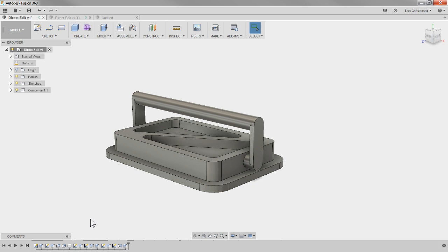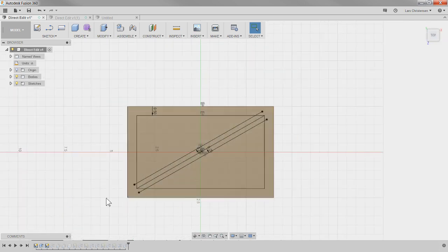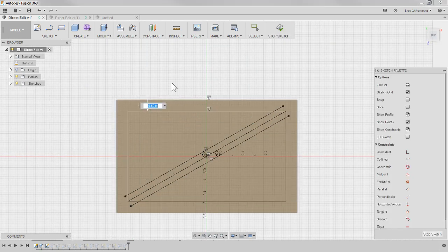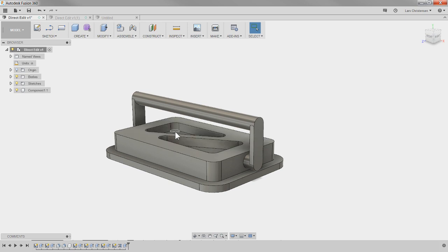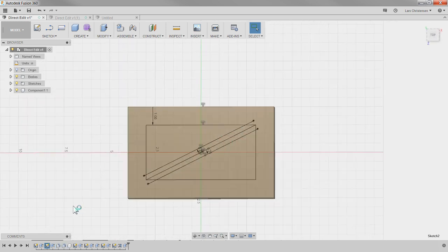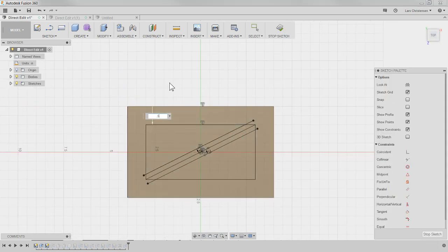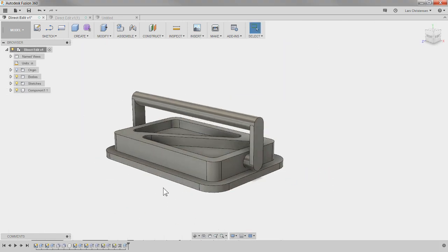So you can go in and change the sketch. If I go into this sketch here, say edit sketch, we could for example change the offset dimension here, make this 1 inch, and now when I get out of it, these 2 pockets got smaller, and I can go back and change it back. That's parametric modeling. That is what I think most of us are used to, and it's what I use all the time.